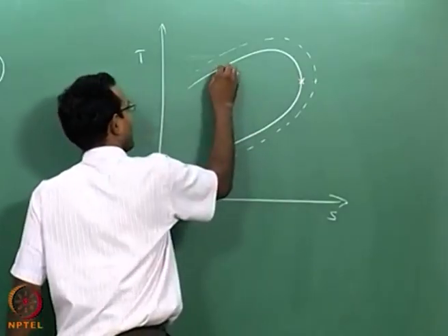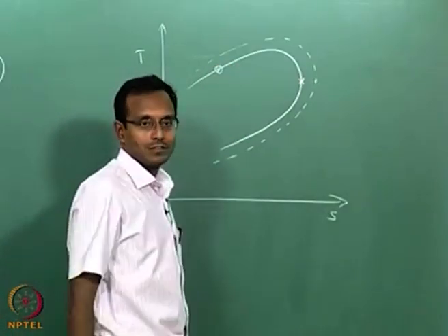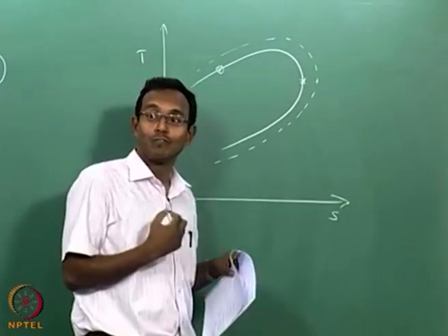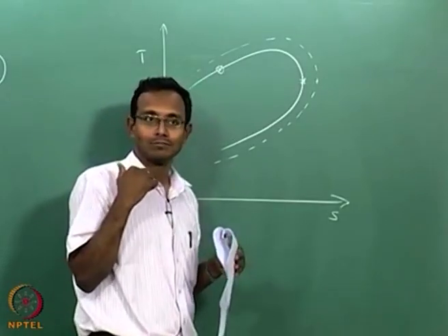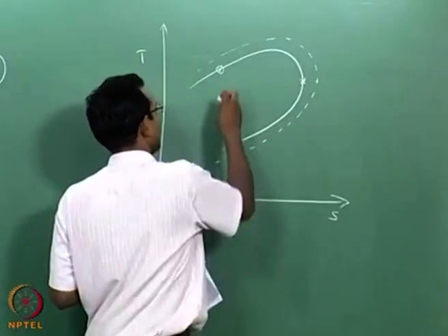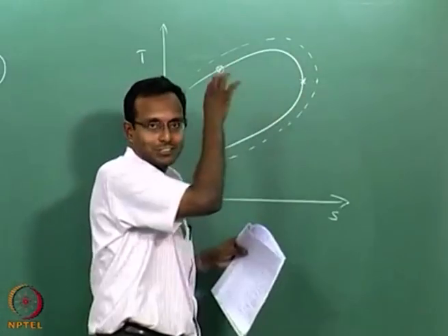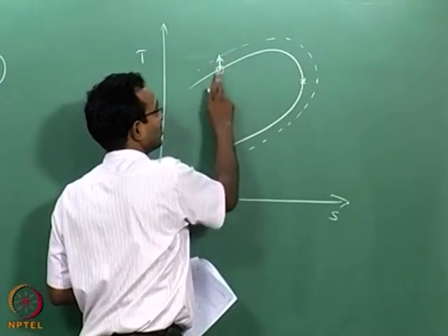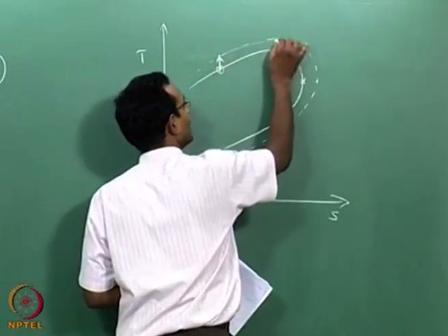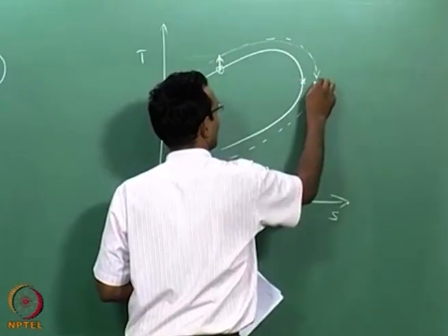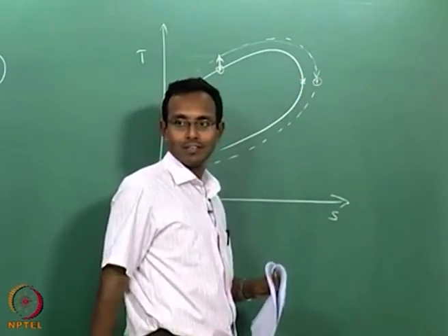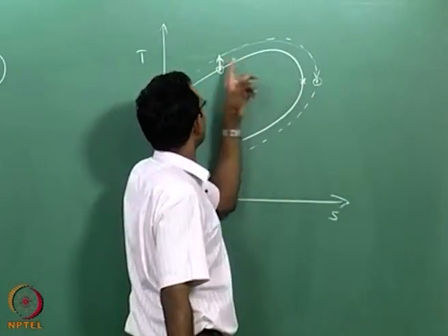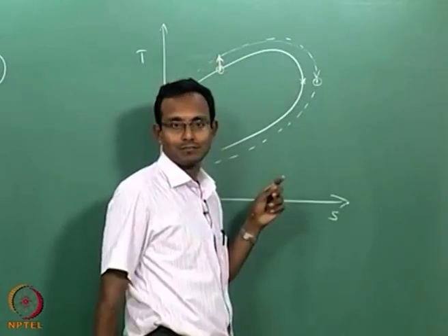So I say I started here, my M1 was initially here, let us say, and I added more fuel than this Q max value. Then immediately what happens is the whole flow field adjusts such that the flow at the inlet itself is decreased, it goes to the next curve, and then now it goes along this curve to reach this point. This is your final state. It reaches M equal to 1, it is going to be choked, but it starts with a lesser mass flow rate.